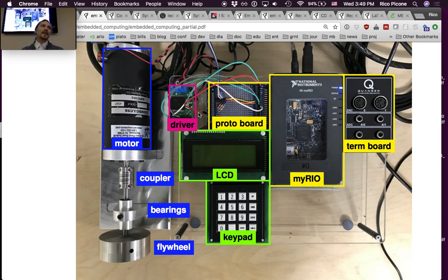You don't want to order custom circuit boards, because there are always minimum orders, and they're getting cheaper, but still you don't want to design it. It's kind of a pain. What you'd rather do is just solder a couple connectors on there and be done. So they sell these breakout boards or evaluation boards that allow you to use that chip without having to develop a full board for it. So really convenient.